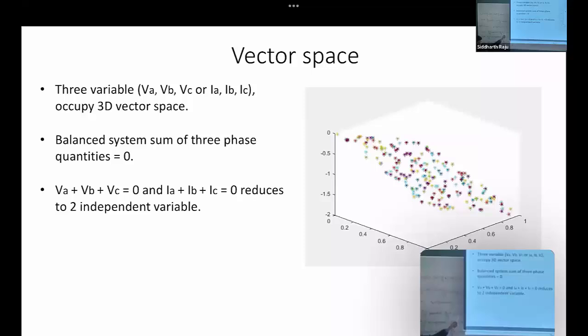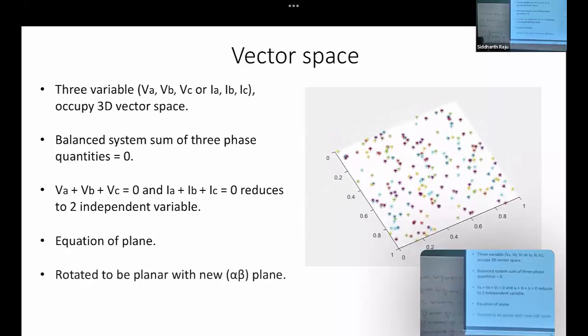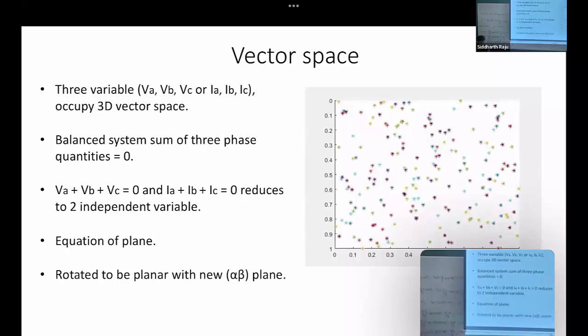So that's how, when I gave two values of current, Leo gave me the answer for the other current, or I don't know who gave the answer for the other current as 14 ampere, because all those values lie on the plane, because the sum of the three is going to be 0, right? So this is basically the equation of a plane, and the space vector transformation that I wrote there, which is basically taking IA times e power j0 plus IB times e power j2 by 3 plus IC times e power j4 by 3, all that's doing is taking this plane and rotating it and showing it to you. That's all that equation is, right? So taking this equation, rotating it and showing it to you.